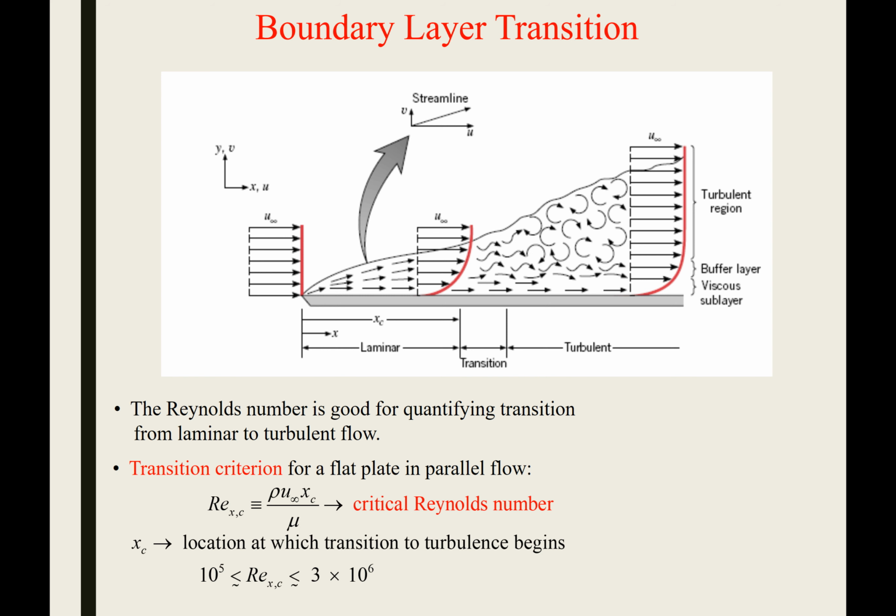So this boundary layer is going to keep on growing and growing until it gets to a point where it's too big to maintain laminar flow. And once it gets so big, some of that fluid's going to start circling back, and it's going to create these eddies, and the flow is going to transition to turbulent. So at some point, and again, keep in mind this is all very theoretical and under really ideal circumstances, that flow is going to transition to being turbulent flow.